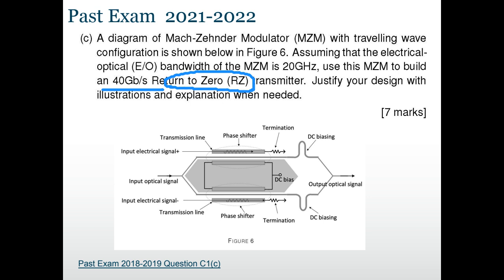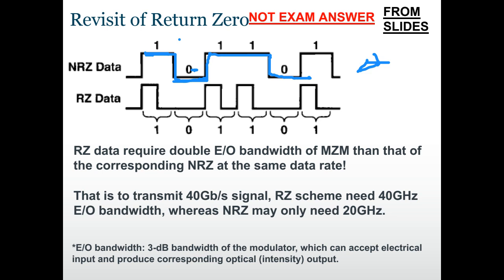So first of all, we look at this page again. For return to zero here, the symbol period is reduced by half. In this way, we created more pulses, more edges of pulses, so the receiver can detect the start of phase better. So it's better for synchronization.